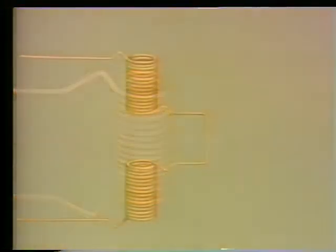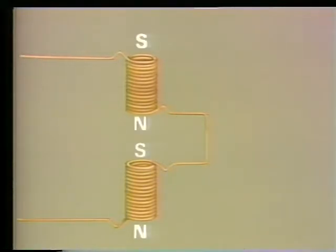But what would happen if we had two coils in series? Most AC motors have at least two coils in series, so let's look at what happens when there are two coils. As current flows through the two coils, they each produce their own magnetic field, and each has a north and south pole.